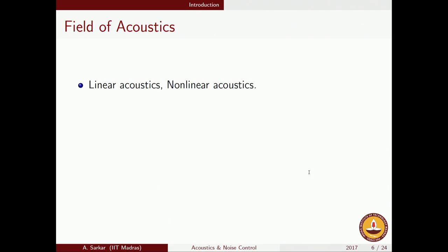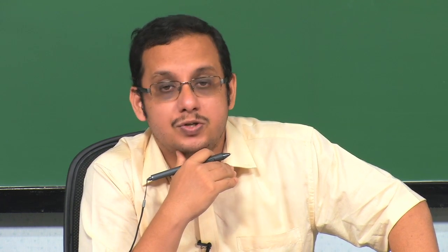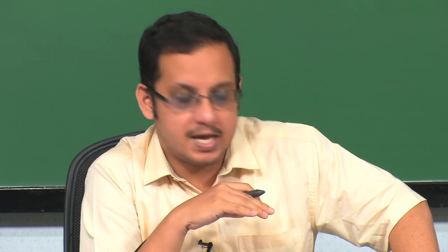Okay. There are different fields associated with acoustics. We will be interested mostly in linear acoustics, because sound which is not too intense will fall within this domain. However, if you have very intense sound, as arising in aerospace applications during launch vehicle takeoff, these intense sounds, which are more than 100 dB or so, should be analyzed as a non-linear acoustic phenomenon. However, this course is only about linear acoustics.